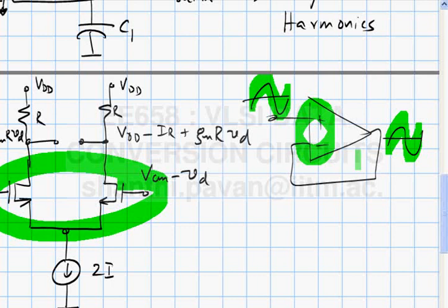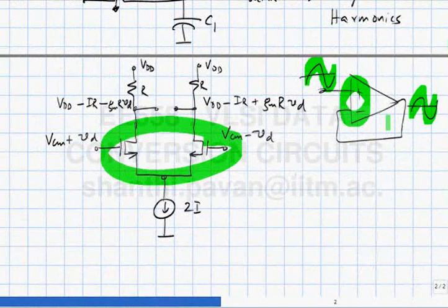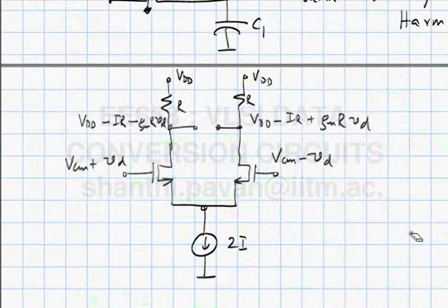The common mode signal is almost the same as the input signal. Correct? So you can see the input is a big swing signal, you can see the common mode will vary. If this current source wasn't there, it will cause the quiescent currents in the transistors to go completely haywire and probably cause complete breakdown of the circuit. Does it make sense? Thanks to the current source here, we see that we are getting a large differential gain equal to GMR, and in principle zero common mode gain as long as the tail current source is ideal.